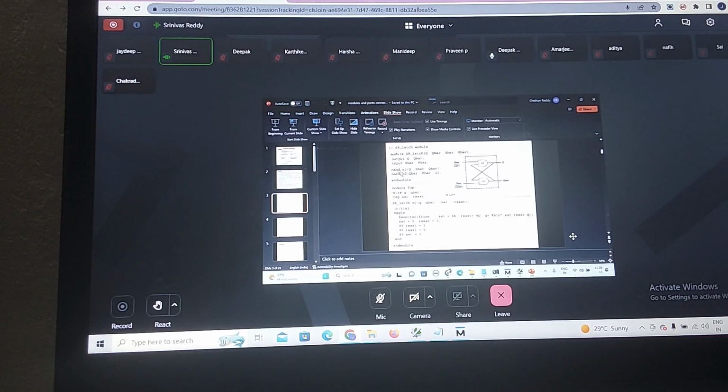Now, if I write the NAND gate output at gate level, what are the outputs? Q. What are the inputs to this? One is S bar, another one is Q bar. So this NAND gate output is what? Q bar. Inputs are what? Q and R bar.